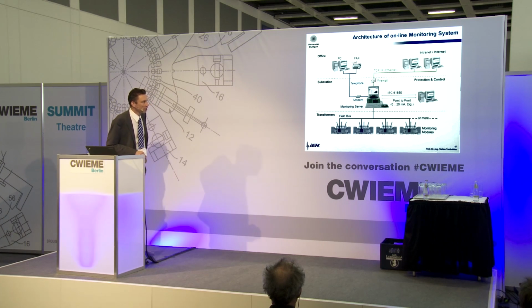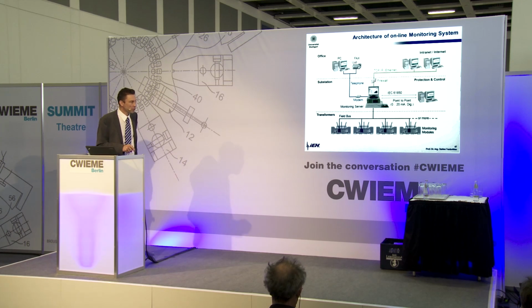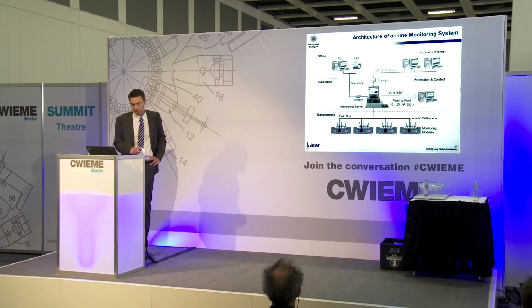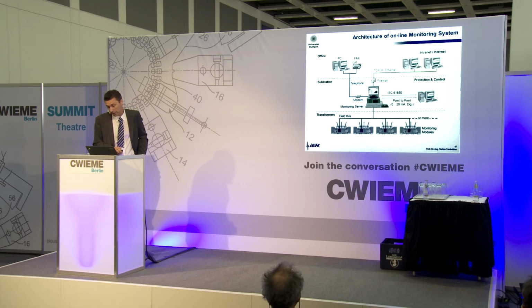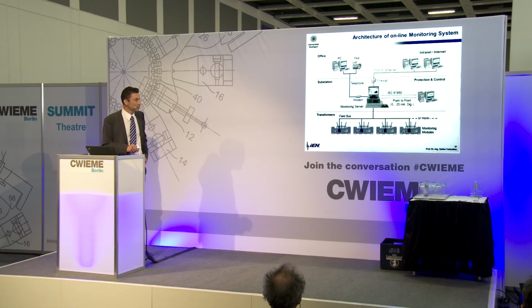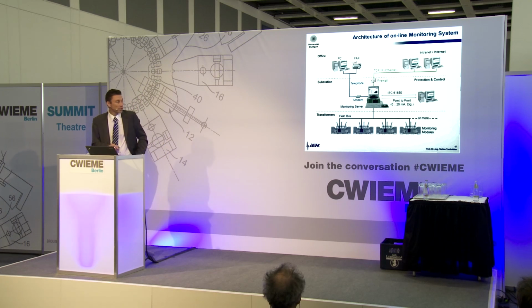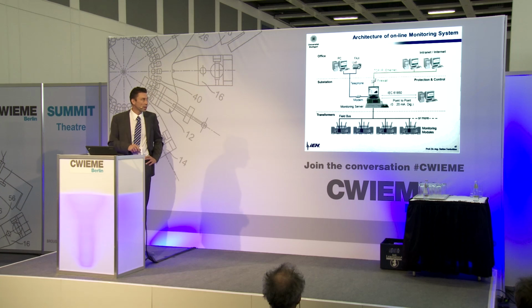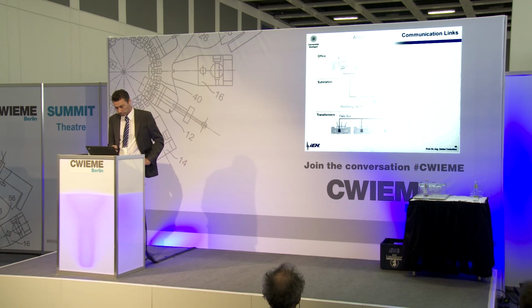This server can then communicate with the protection and control system by means of digital protocols, for example, the new IEC 61850 protocol, or in former times, if there was not such a good communication link, also via modem and telephone line, but also, of course, with TCP/IP, with the intranet and the internet.